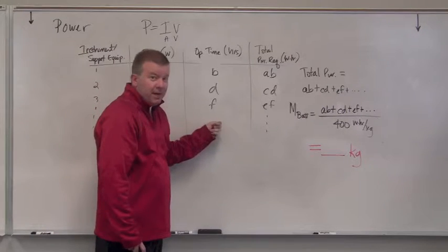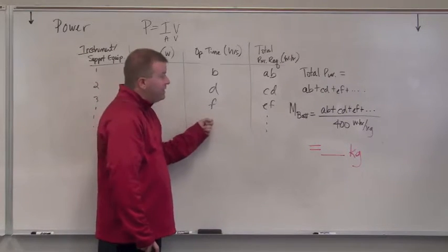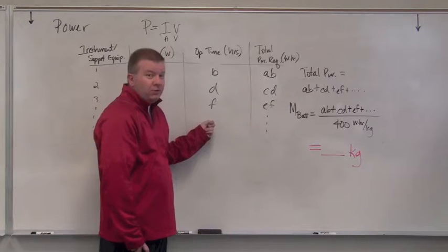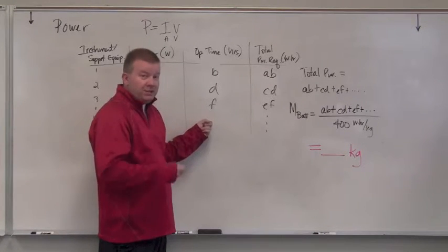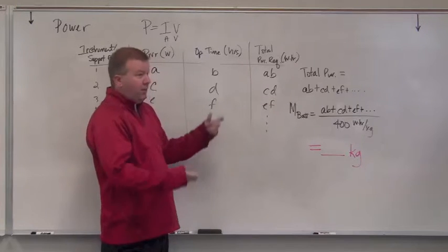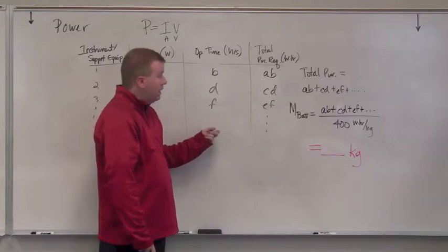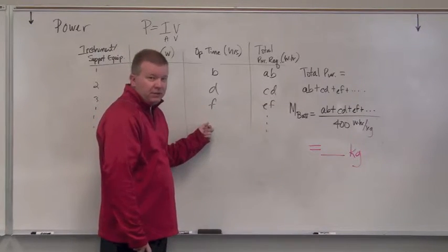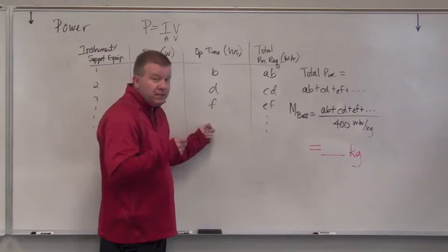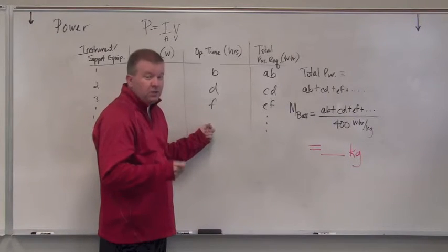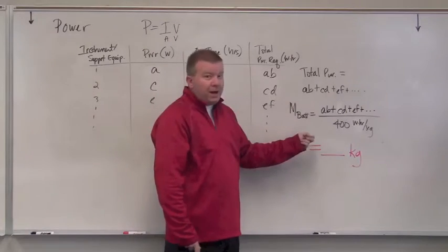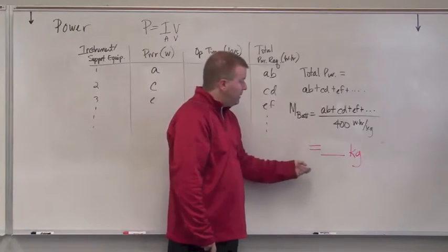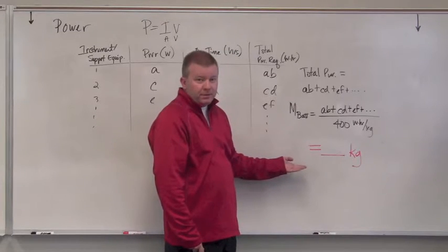This operating time, I'm not going to stress this enough. This is your calculation of how long you need to last, okay? And it should be based on engineering analysis. It shouldn't be, well, I think it's going to be 5 seconds. No, it should be based on engineering analysis of when does your mission begin and when does it end. You should be able to calculate that by now. With that known, divide by 400, sum them up, divide by 400, you got the battery mass, okay?